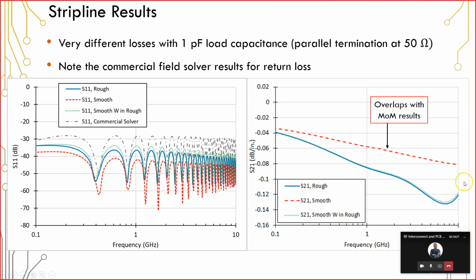solver, or most solvers, I should say, are not actually predicting this S21 profile. So this is something that you need to calculate by hand, or you have to use maybe a more advanced solver to simulate this S21 curve. So I'm going to show you an example of how to calculate this by hand in just a moment. But it's important to note that if you're using a calculator application, it may not actually calculate this attenuation for you.